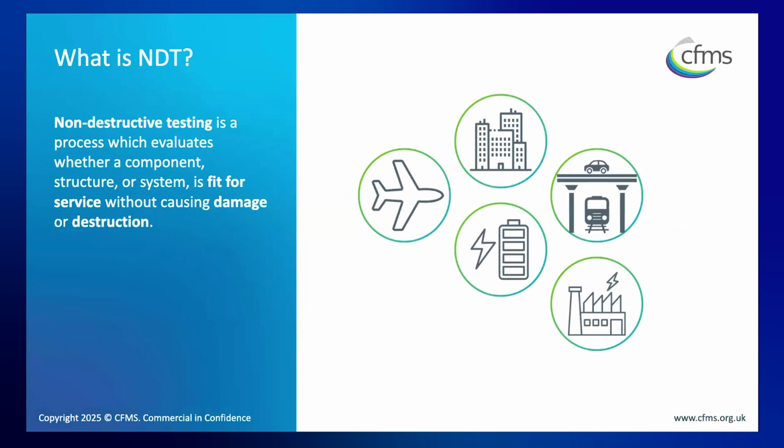So briefly, what is non-destructive testing? It refers to a process or a methodology which evaluates whether a component or structure or system is fit for service, particularly without causing damage or destruction. A lot of the technologies that would be used for NDT are shared with medical diagnostics, so things like radiography or X-ray testing, ultrasound, that kind of thing, to inspect the component.